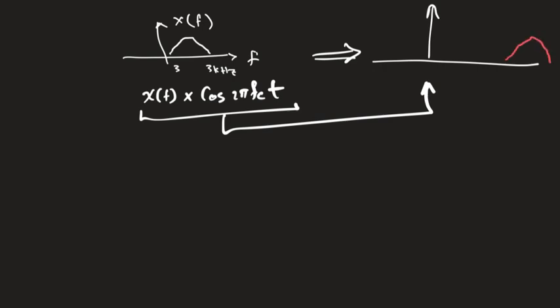right? This is where it was originally. Maybe this is the center point. And if I look at the new center point, the distance between those two is going to be this carrier value. Okay, so the signal from a frequency domain perspective has been shifted up in frequency. Okay, this one is F minus FC. It shifts up in frequency, right?